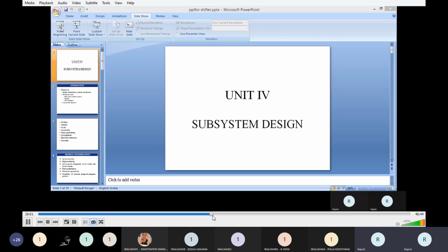So there must be some design methodology. What is the design methodology? You have to go in a flow. First you have to analyze what is your top module, what is the sub module, what is the next sub module, and how you start designing. So you can go for top-down design approach by using some CAD tools. Then partition the system sensibly.